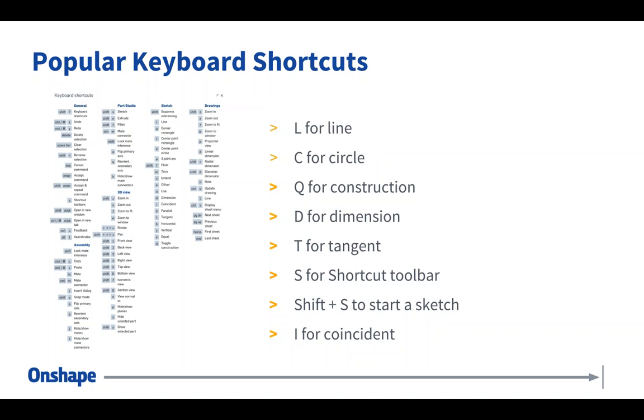Another favorite that I mentioned earlier is the N key for normal to. Everyone's going to have their own preferences, but definitely check out the keyboard shortcuts. They can make a huge difference in the design time, the day-to-day stuff, clicking commands and so on, which again, small improvements make a big difference when we talk about doing them over and over and over again.